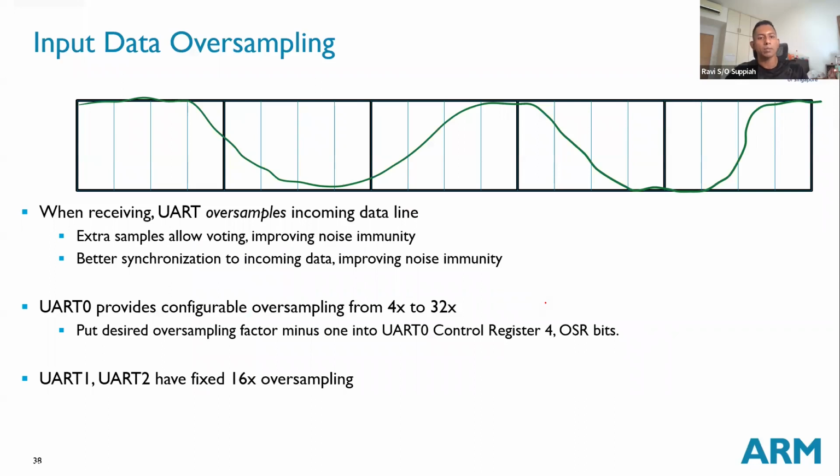Now, how do you deal with handling noise? Whenever you transmit data across a channel, within the board itself it is usually quite safe. Even though things can still go wrong, it is still very safe. But once you bring data out, that means from the microcontroller you connect a wire out to some other board or some other component, there is a lot of noise that will interfere with the signal coming in.